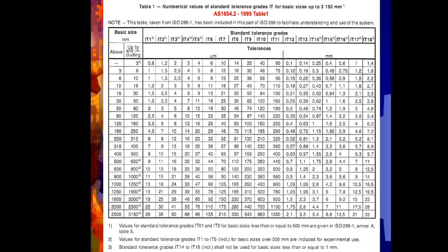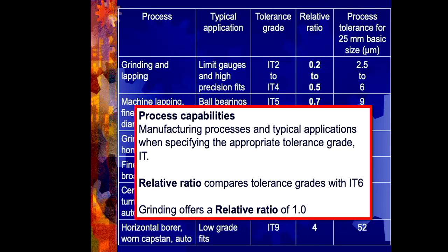And there it is. Now, years ago, this subject had an open book exam. More recently, it's been closed book. The rise of social media has certainly played a big role in that. But this subject is not about memorising by and large. It's about understanding how to do stuff. And that's the chart that you will see in the back of your exam if there is a tolerance in question. Using it is what I'll be looking for. One more thing, micrometers, and then we get to a certain point, we go to millimetres. So 60 micrometers, 100 micrometers, or 0.1 millimetre at that dividing line. Always be aware of the units.